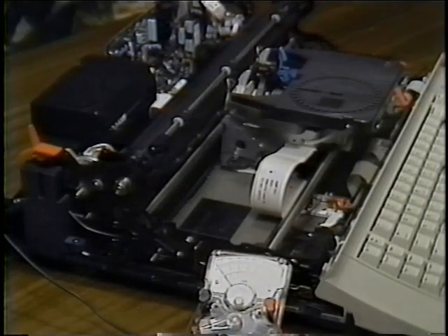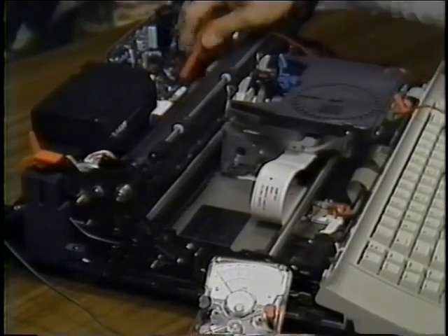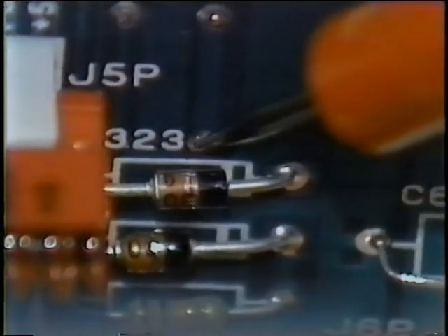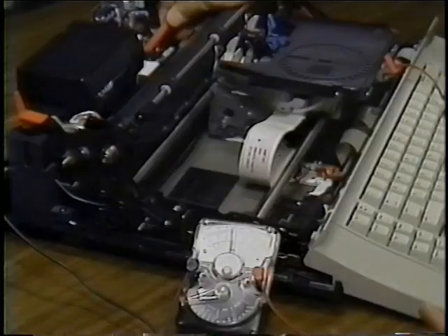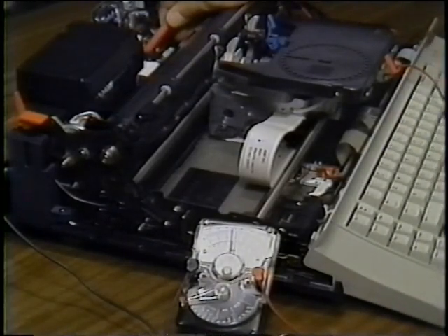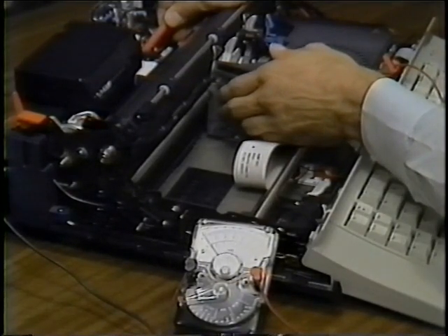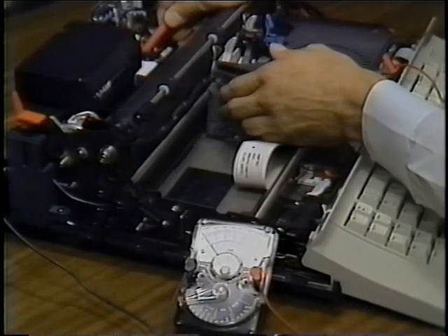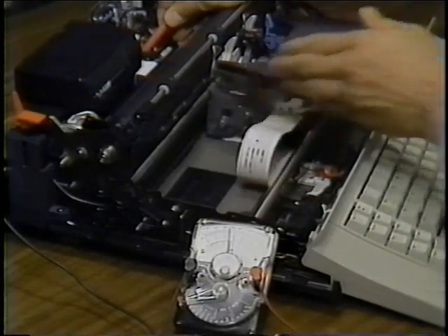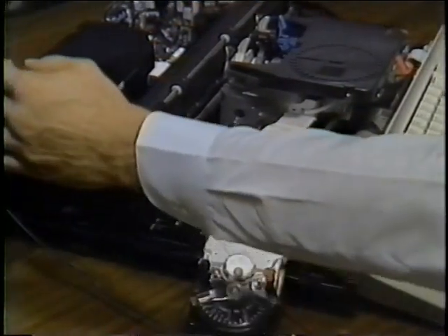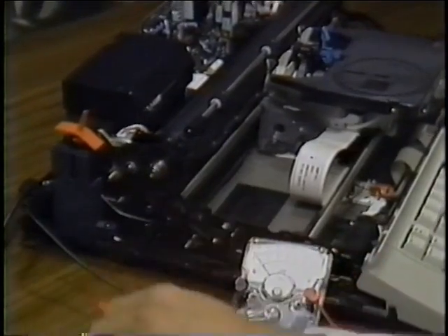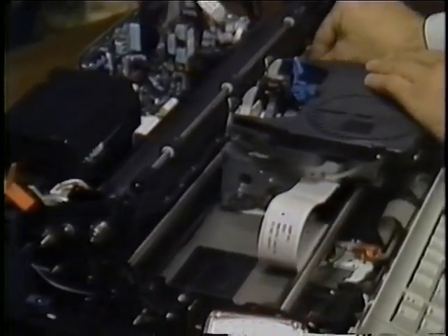With the meter set on the 12-volt DC scale, place the VOM meter lead on the sense pad on the printer board. When the homing sensor is not blocked, the meter should read from 3 to 5 volts DC. Press the homing flag in slowly. When the flag blocks the homing sensor, the meter should read from 0 to 1 volt DC. Turn the machine off, and reinstall the transport belt.